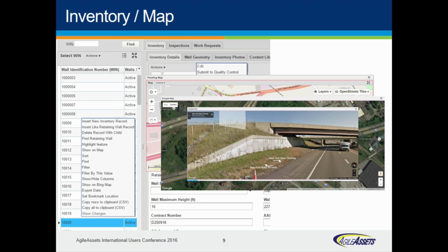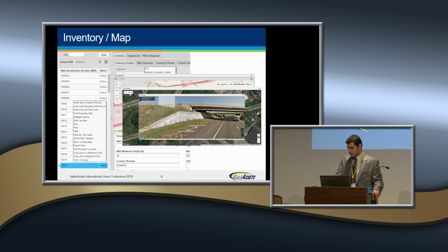In version 7.2, as many of you have noticed during other presentations, our mapping functionality is going to be interactive. And one more thing about mapping and location of assets is that in this framework we support both location systems for these secondary assets. It supports lat, long, XYs, and we also have LRS, route, mile point, from, and to, and spatial is going to be the major one. It is entered and kept as the master record, and the LRS ones are calculated automatically from spatial information.